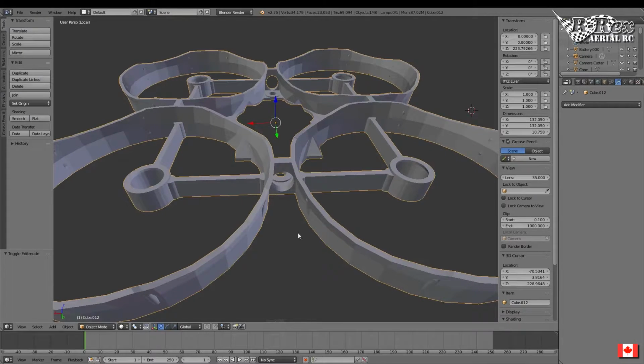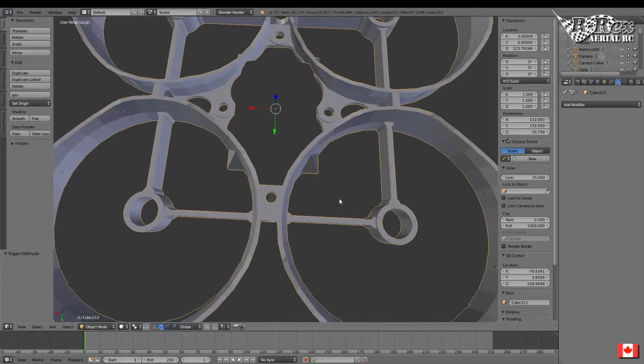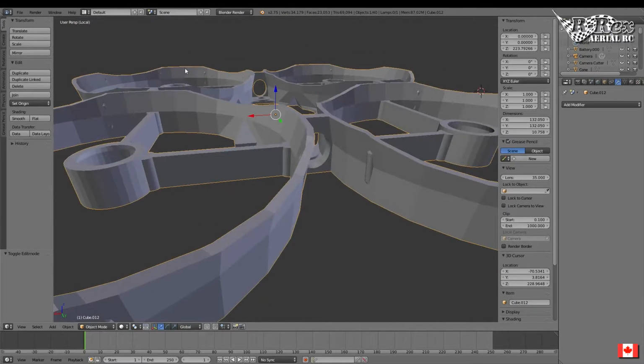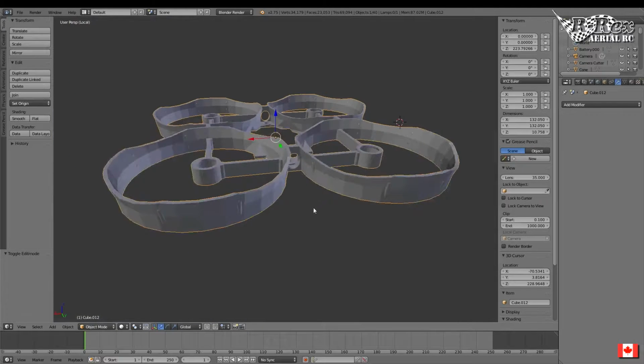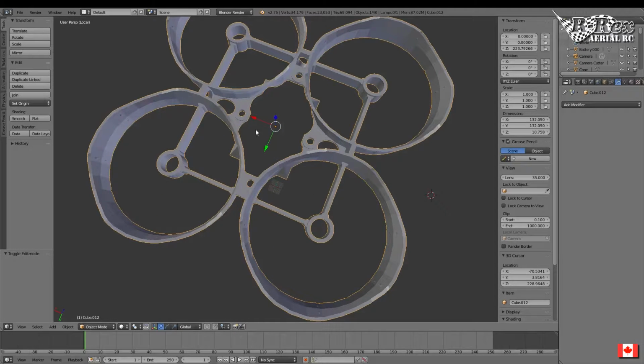So I actually went a little bit more when I did this model. Well, first of all, I cut out more spaces like this, which was just basically I created cylinders, laid them on 45-degree angles, and cut out to make these notches. You already know how I made these holes. These are where the nylon standoffs actually go, as it's built in layers.